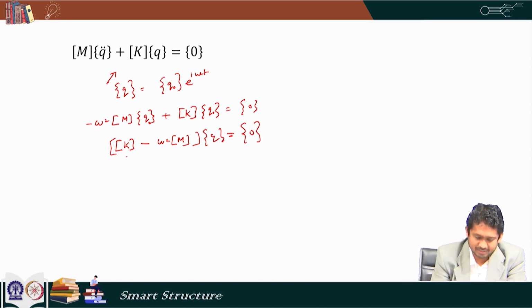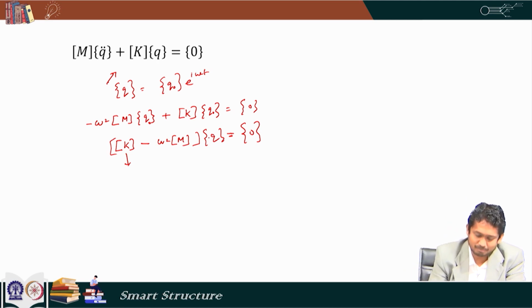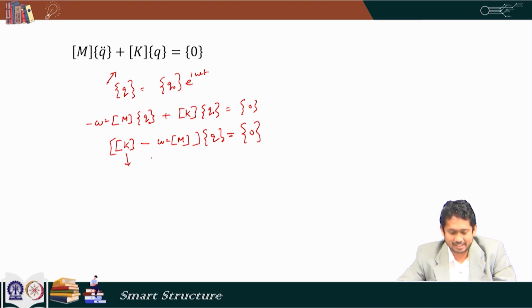Here one thing to note is that this K has contribution from the shear in the fluid layer, and the shear modulus of the fluid layer was a complex function. So, by solving this eigenvalue problem from the eigenvalues, we can estimate the damping present in the system. For different values of the electric field, we can find how the damping changes in the system, and that kind of study can be done from this equation.